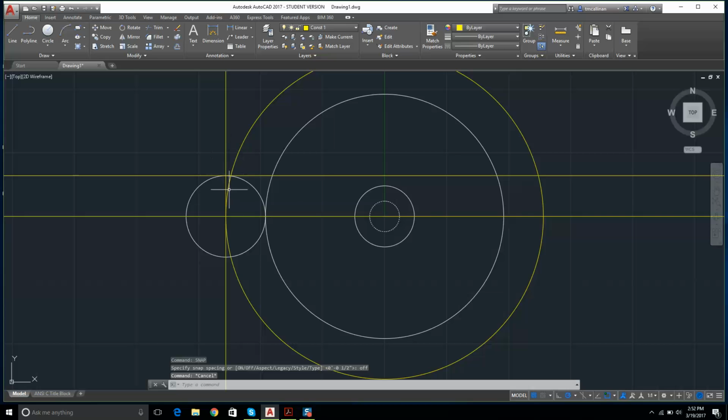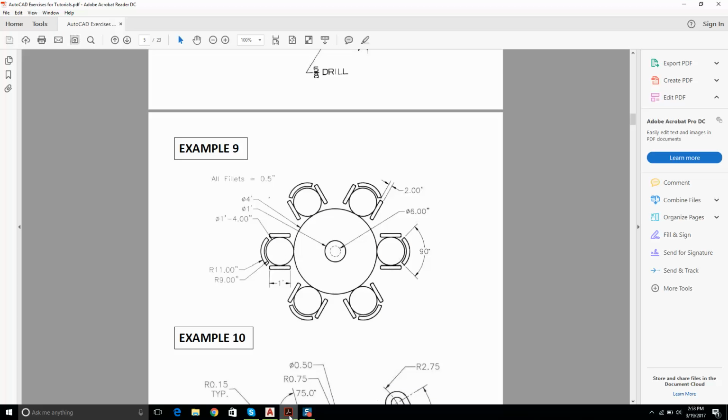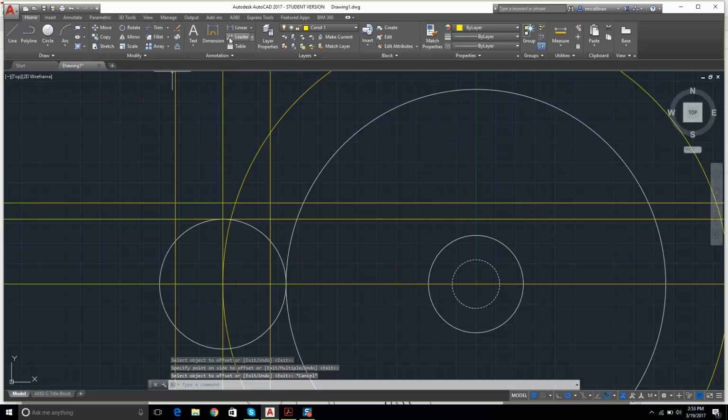Okay. So we got this, and 1 foot is the length of the armrest. So I'm going to offset. It's 1 foot, so excuse me, 6 inches to there and to there. Now, what's the width of it? It looks like a thickness of 2 inches. So I'll offset this 2 inches to there, and I'll get myself on the 0 layer. I'll get myself a rectangle. There we go.